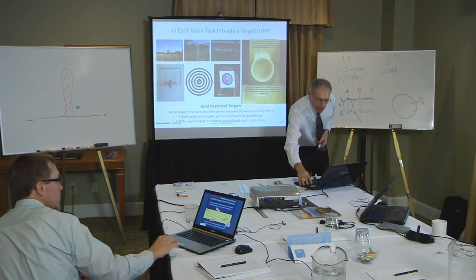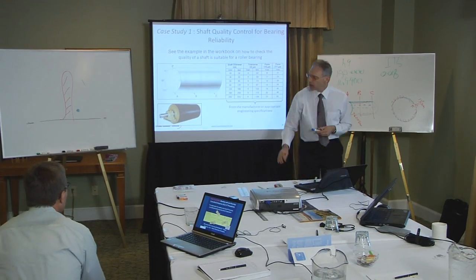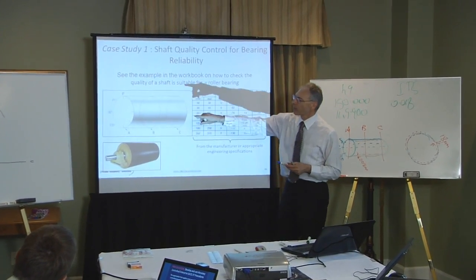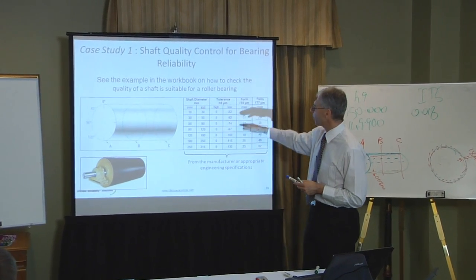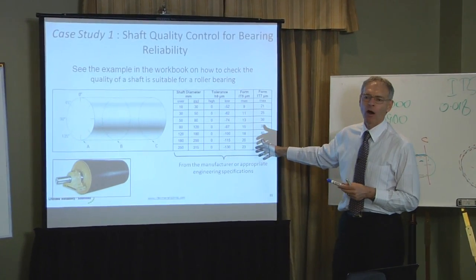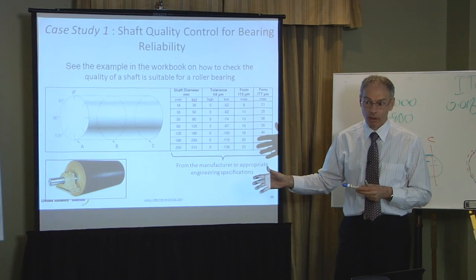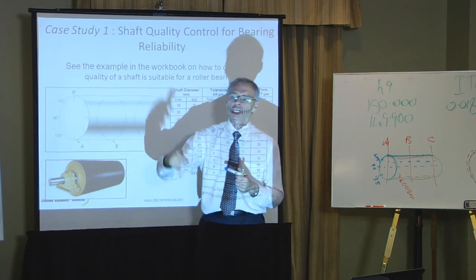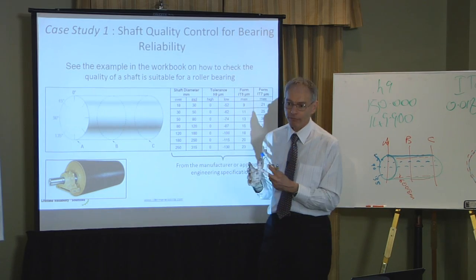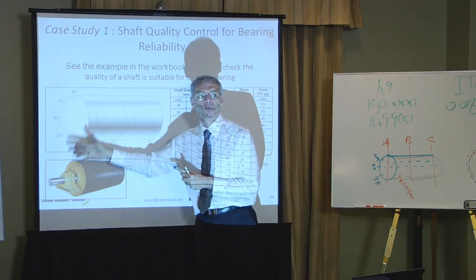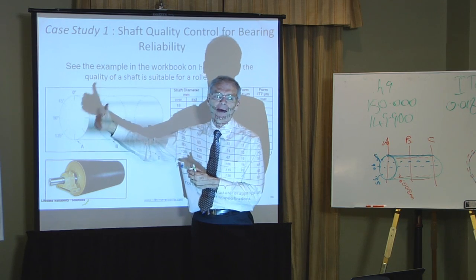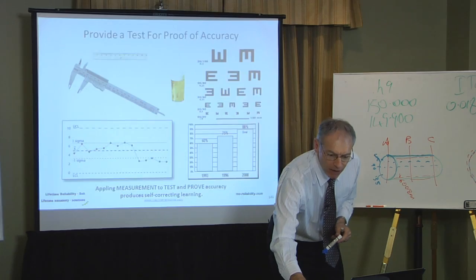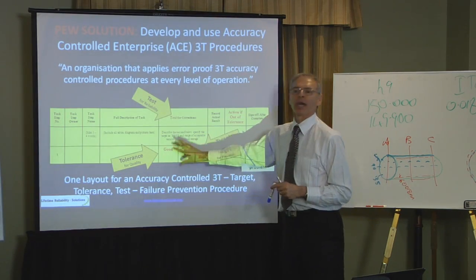So back up here, when we had our shaft and the tolerance was unacceptable, in my procedure it would say, okay, if the shaft is not H9 or not IT5, replace it. Or take the shaft out, go back to the workshop, machine a sleeve up and re-sleeve. And then we'll buy a new shaft for you next time we have a shutdown. So I want to tell the guys what to do if it's out of tolerance. If it's in tolerance, we're going to use it.